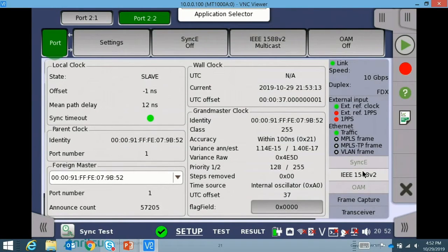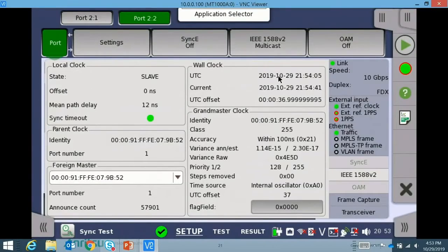Okay. And if you're wondering, the way I'm able to show this measurement is I'm connected to myself. I mentioned earlier, when you have a resource, one of the important parts is to make sure that you have a grandmaster clock reference. That's what the tester is able to do. It's able to do both the grandmaster as well as emulate that of the slave. So what I'm doing is going grandmaster to slave in a port-to-port application. All I'm measuring is myself from point A, from my grandmaster, to the slave that I'm emulating. What do those messages look like?